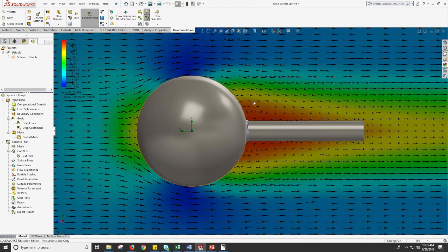And this is a zone of turbulent wake. All right, pretty cool stuff. And this is the thing that you could take the screenshot of. These colors and the size and density of the arrows is going to change as you go from 10 miles an hour all the way up to whatever the top speed you're comfortable with, 140 miles an hour for our wind tunnel. So this is the idea of what the results are going to look like, and that's pretty cool.